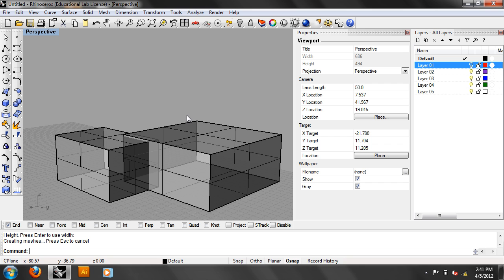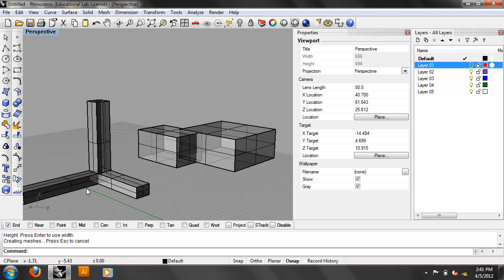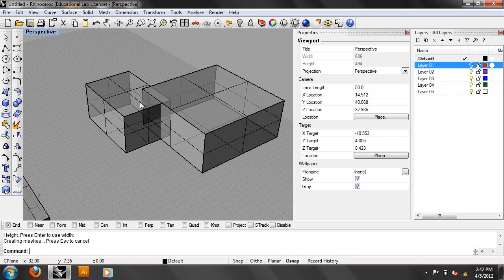So if you want to do a Boolean on this guy, you really want that thing to be a solid and not three things, because otherwise you get three things that have been Booleaned instead of one thing that's been Booleaned. So if you want to use Booleans, you have to play with solids. You can Boolean a surface, but I think when you do it, you're thinking of solid operations. Does that make sense? You really want this to be clean, because then it's going to produce a clean Boolean later if I want to Boolean a sphere out of it or something.